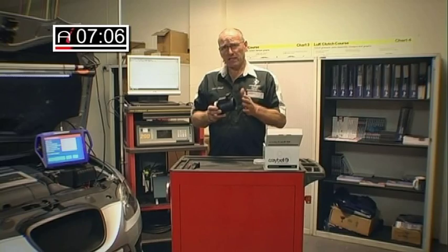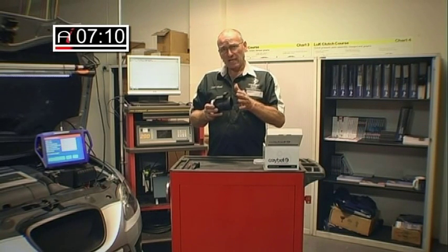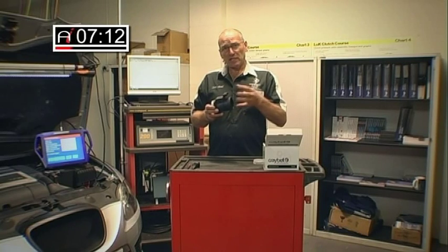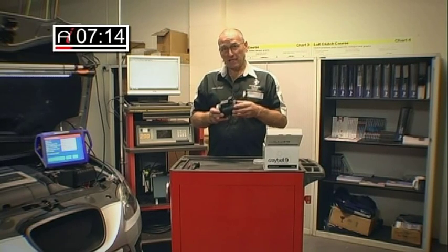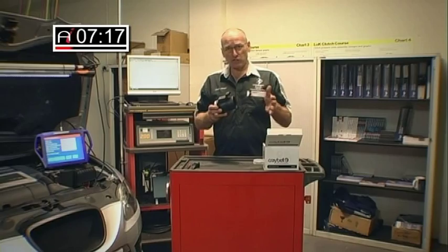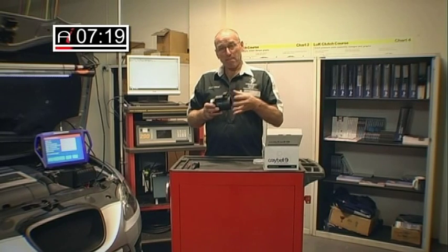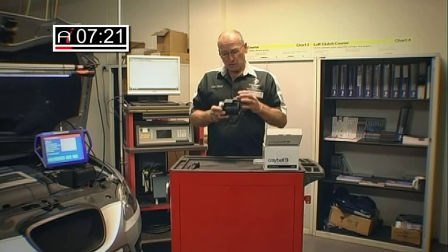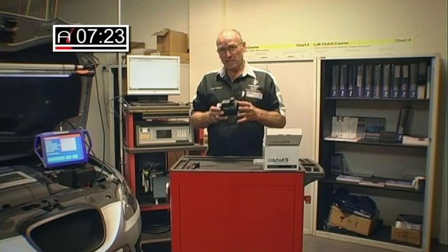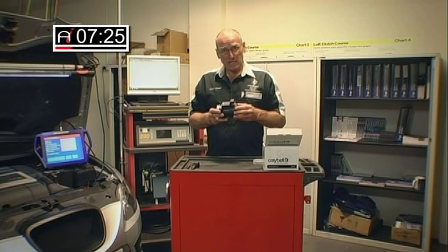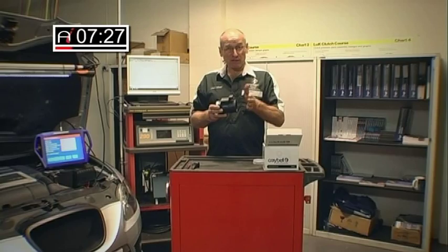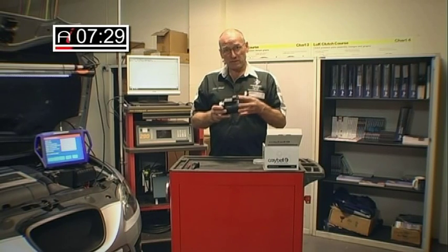You may often find on petrol engines, if you look behind the actual throttle butterfly, it's quite dirty, whereas the leading edge, the front edge, is actually quite clean, and that's because it's the fumes from the engine that are attempting to get back into the induction system. So contamination from a petrol system is not as severe as diesel, because it at least has the throttle butterfly to prevent some of the contamination.